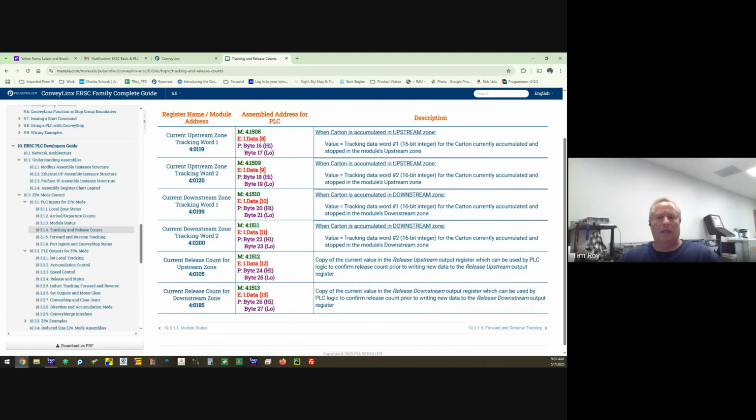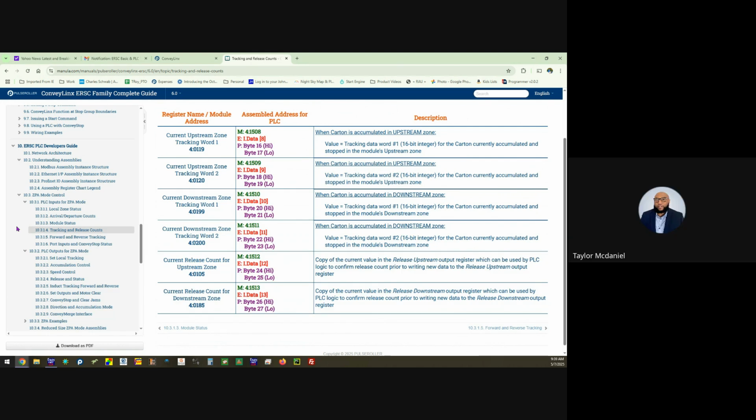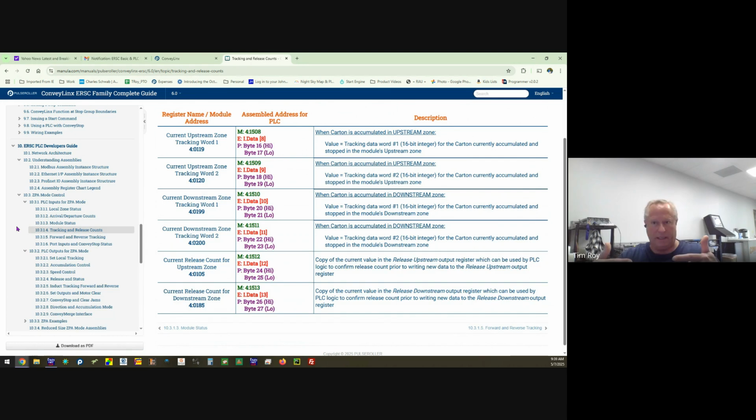So what happens is the actual tag in the add-on is a DINT. So you can either write a big number, or what we suggest, use two smaller numbers, one in the high word and one in the low word, which comes back to the crazy part of, well, if you want to use them separately, why did you combine them?